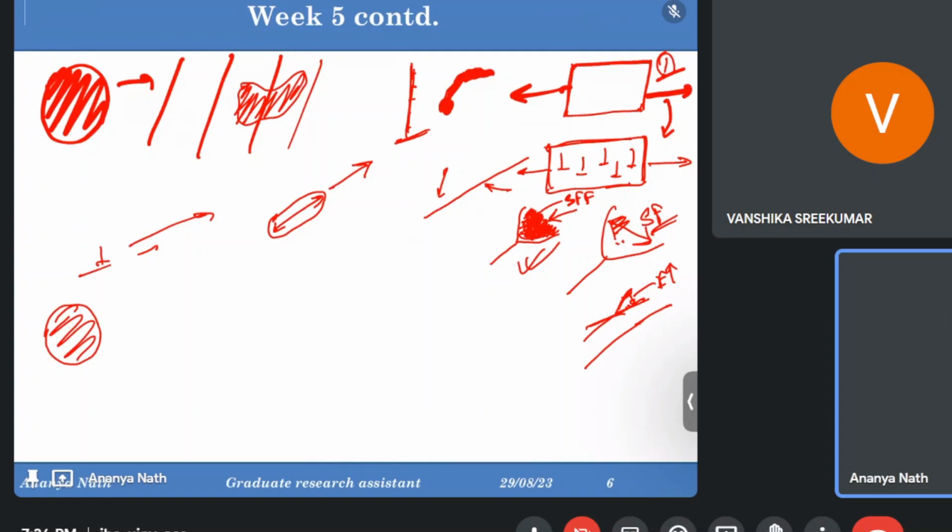So strain free grain typically means there is no dislocation in the particular grain. Strain is a word which is always associated with the dislocations. Strain free means there is a grain which is having a particular grain lattice. The lattices inside the grain are arranged in a particular direction, and in all the lattices inside that particular grain there is no mismatch or no dislocation.